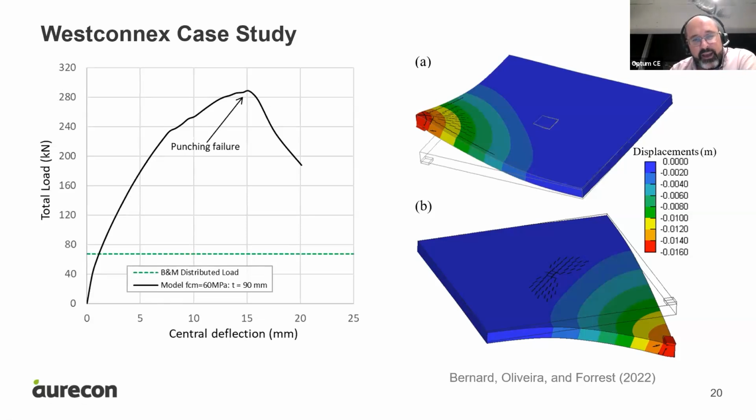And similar values apply also for the SLS, right? So you see here an enhancement of about 4 or 5 times in capacity, or even more. And the actual failure here was the punching of the load, in this particular model. Obviously, when you see this amount of enhancement, like 5 times what we thought we would have, you get a bit worried. So we don't completely just rely on modeling.